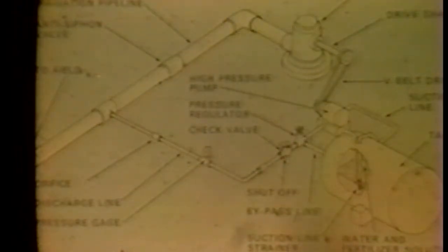Similarly, evaporative cooling is used to lower the temperature surrounding plants during excessively hot days. Another fringe benefit is the application of chemicals to crops through an irrigation system. Fertilizers, herbicides, and pesticides may be injected directly into the irrigation water. This is done by use of a high-pressure pump and a tank that holds the chemical solution. Also, animal wastes in liquid form can be applied or distributed through an irrigation system.